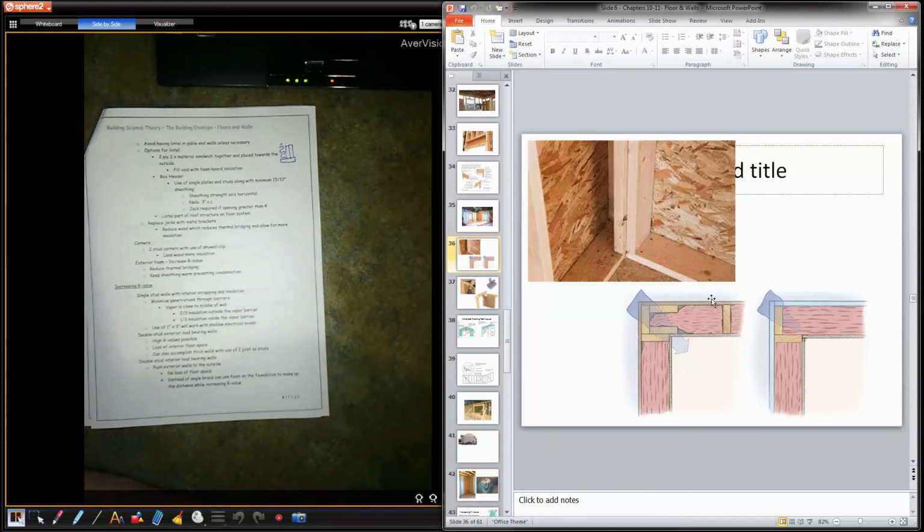When I install the insulation into a corner like this, I normally cut a piece to fit from here to here to here. I install that piece of insulation first, then I cut another piece to fit from here to here. When I cut a piece of insulation, I oversize it by 1/2 inch. Same thing here, oversize it by 1/2 inch. Put that in, then I put this second piece in after, avoiding the insulation having to do one of these curls that is being compressed here and doesn't look very good. I like having my insulation touch the 6mm poly.